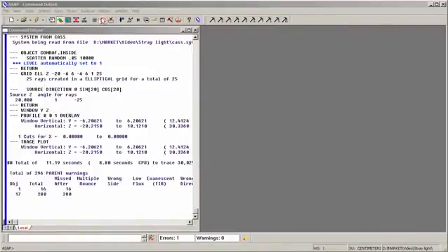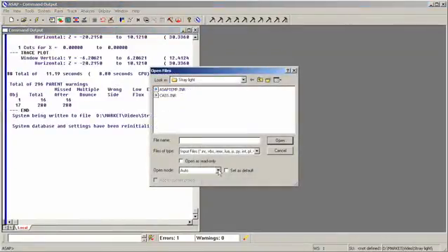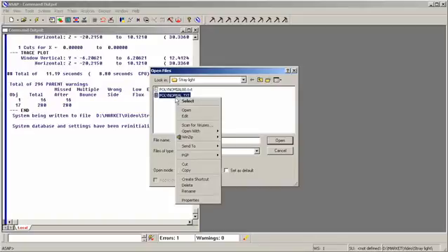Let's take our measured data and fit it to find the coefficients. Let's do this by opening up a file within ASAP. We go over here to our ASAP file. BRDF fit utility is the application that we're going to use, and we're looking for text files. I have here some text files which represent the measured data for the black surfaces that we saw before. Let's take a look at one of these text files before we first open it up.